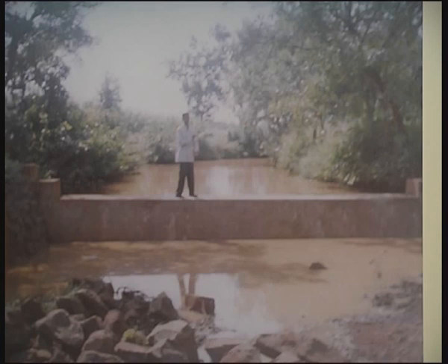Spreading techniques are to be adopted for the purpose of increased recharge. In the case of a check dam, the water spread is very small because it is confined to the stream course, and usually it would be 1 hectare or half a hectare. And when such is the small water spread area, the amount of recharge through this water spread area would also have limitations.